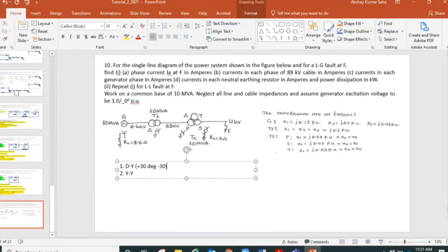We call it Y or 1, call it 11 or 1, corresponding to the clock, like the clock that we put on our walls. The hands are there, minute, second, hour. If we think that 12 o'clock is the reference, then if we go to 1 o'clock, we get a 30-degree difference between 12 o'clock and 1 o'clock. If we go to 11 o'clock, we get plus 30 difference.